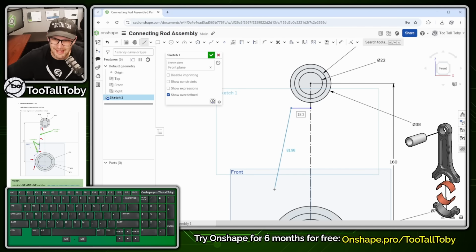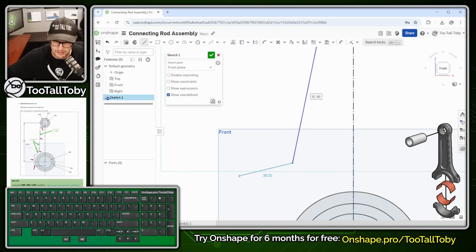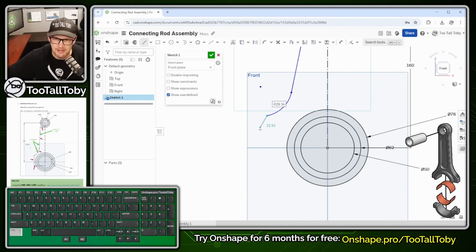So we're going to create an angled line here. There's no relationships on the line. We're going to single click, and then we're going to move our mouse away from that end point. So you can see here, we're moving away from that end point, put our mouse over the end point without clicking anything, move away again, and that lets us create a tangent arc coming off of that end point. And once we create that tangent arc and left click, now we're back in the line command.